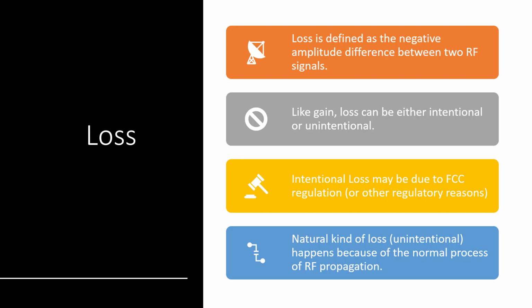So what do you do? Go and do a field trial. Go and do signal analysis. Do some site survey. Based on the site survey, obtain your results, table the results, and see how you can use this gain and loss function to equalize to the state that you want.